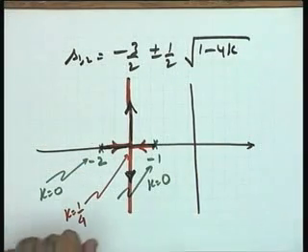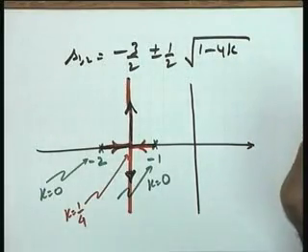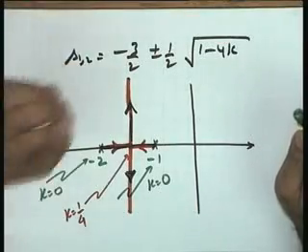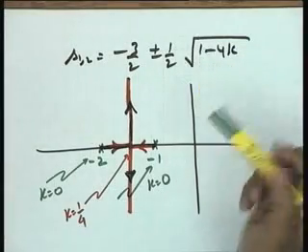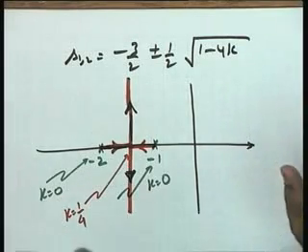So what I want to say is this, that whatever information you wanted to have about a system in terms of rise time, settling time, peak overshoot, zeta, omega n, this is clearly visible in this form in the root locus plot. And how? First of all, from the root locus plot it is very clear that for any value of k from 0 to infinity, the system will never become unstable, because the closed loop pole will never cross the j omega axis. See the conclusions.